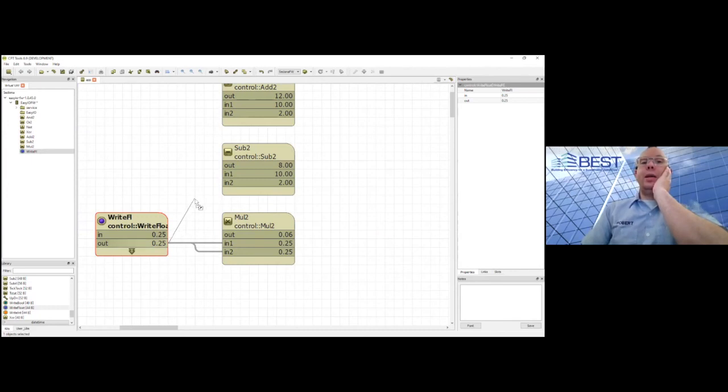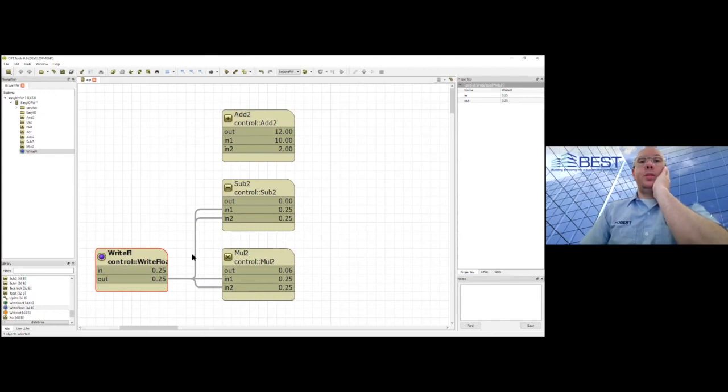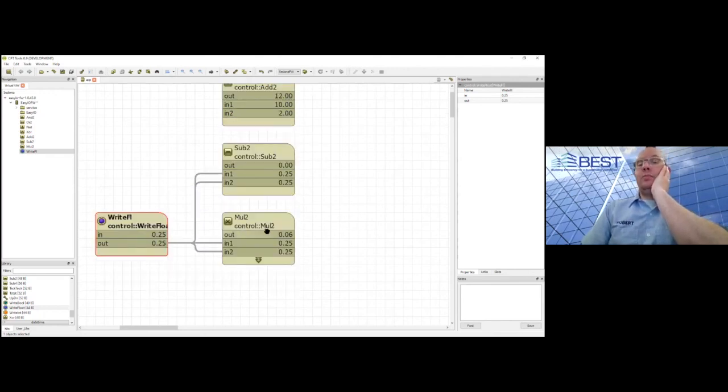And we're going to click and drag and drop it over on the words of where we want to connect it. So I want to drop it to this in 1, so I'm going to drop it onto the word, and it connects. If you try and drop it over onto the number, see the no smoking sign, it's not going to let you do it. Always onto the words. And that's one that is well worth driving home into your students' heads. So when we need to square a value, just multiply it by itself, give it to both references.